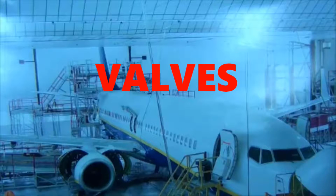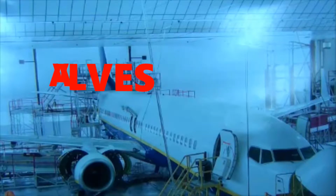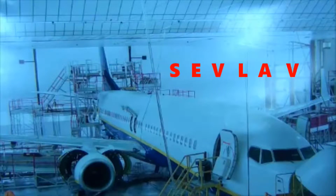And then you also have the low pressure shutoff valves. Those are going to be in effect when the fire push button's released, because you don't want fuel continuing to flow, right? When there's a potential fire, you're adding fuel to the fire, right? So you don't want that. So there's that low pressure shutoff valve. Those shutoff valves are going to be shutting off that fuel to the engine.